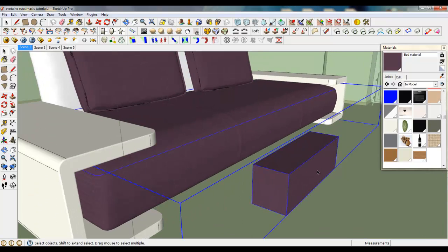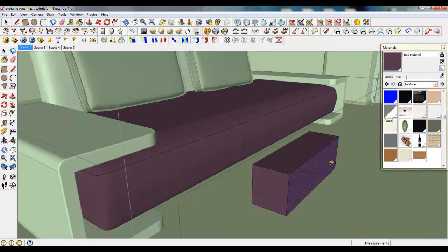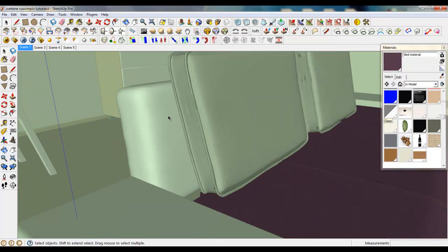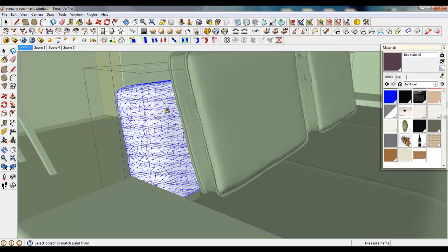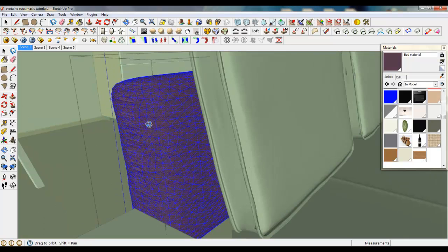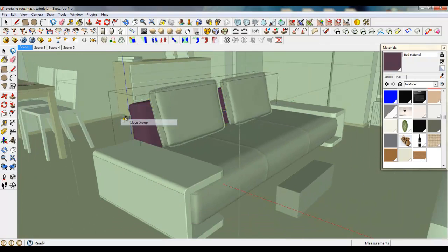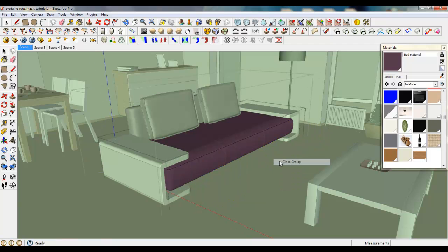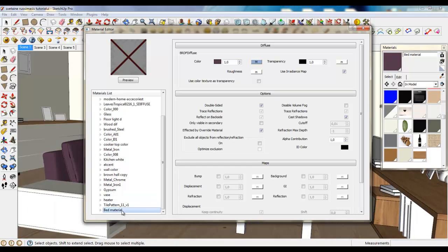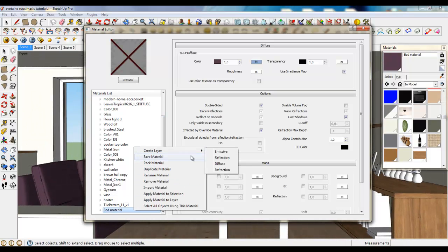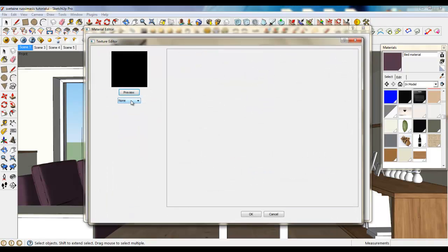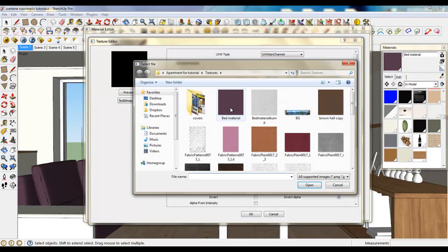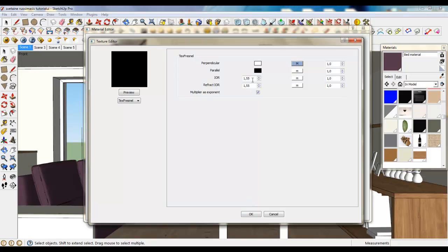Also you can grab this position and open this couch, select the paint bucket and do this. It's good. We can now delete this box. Go to position and bed material. For the bed material we are going to use reflection, add some Fresnel map and shader, texture itself. It's okay. Maybe let's decrease this value.